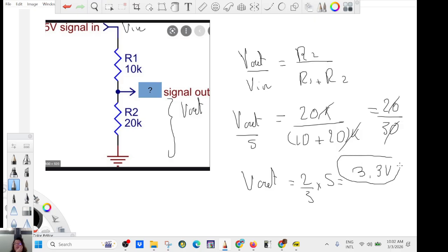And if you play with Arduino or microcontroller, many little sensors, they don't want 5 volt, they want 3.3 volt. So you are using a voltage divider. So this is 3.3 volt. That's going to be 1.7 volts, something like this.